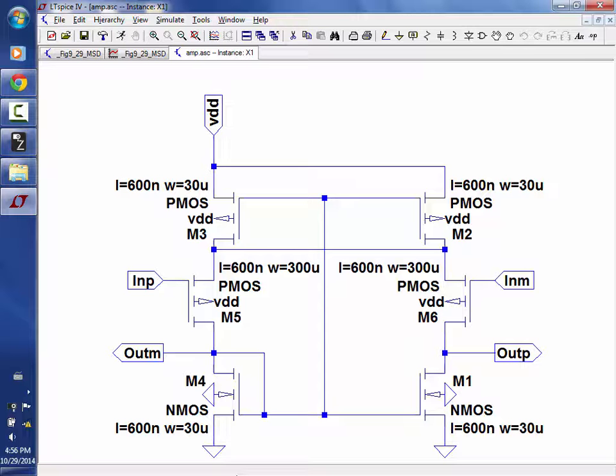So I'm not saying you can't do it. I'm just saying you're going to chase your tail if you just put 2 diff amps together and think that's going to work. Okay? Because it's a classic problem. You understand why, right? Yeah, because you have the 2 poles you can't get rid of. They're at the same frequency. You will have 180-degree phase shift in the feedback.